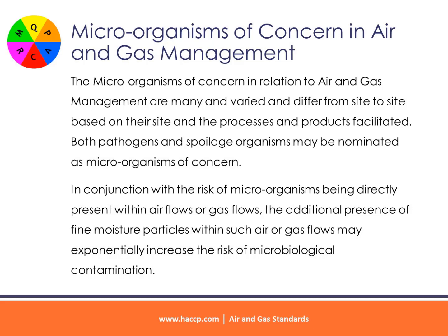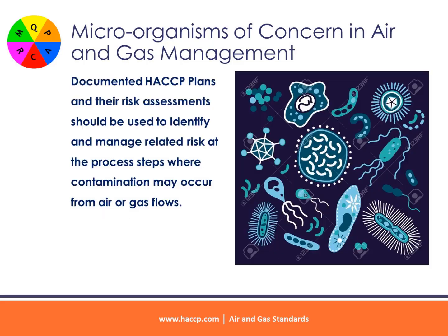In conjunction with the risk of microorganisms being directly present within air flows or gas flows, the additional presence of fine moisture particles within such air or gas flows may exponentially increase the risk of microbiological contamination. Documented HACCP plans and their risk assessments should be used to identify and manage related risk at the process steps where contamination may occur from air or gas flows.